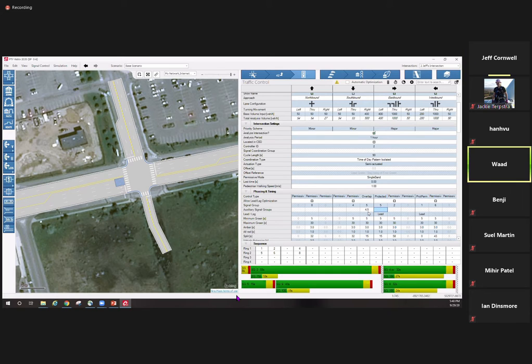Okay. So phase 5 is the eastbound left, so that's the phase it would conflict with. Or sorry, that's the phase that it would go with, right? So if people are turning left here, and then these people are stopped, then we can allow the right turns to proceed. So I wanted to bring that up just so I could show you guys how to put in an auxiliary signal group there. So that would be how you do that.